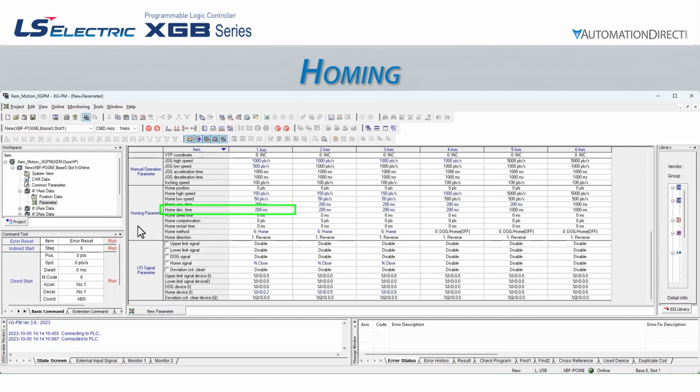Home accel and decel times are the time in milliseconds it takes for the axis to reach full speed or full stop during a home movement. Home dwell time is used when the motion system has a small amount of system lag or mechanical deadband. At the end of any decel function, there may be a slight position drift even after pulses or motion have stopped being commanded. The home dwell time is used to allow the drivetrain to cease motion prior to home being completed.